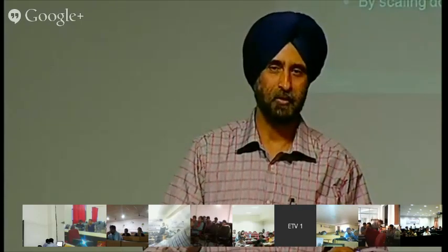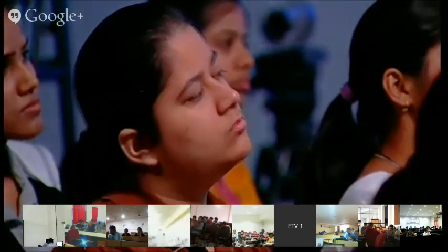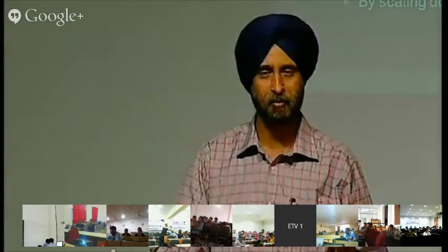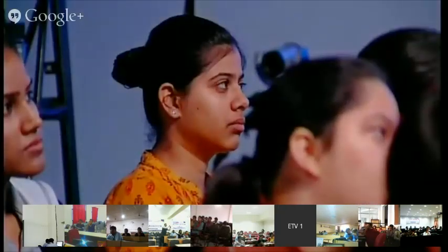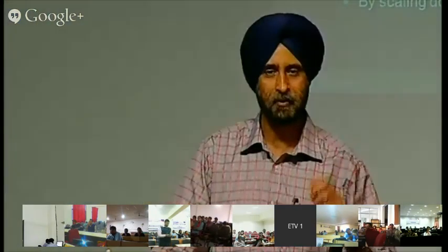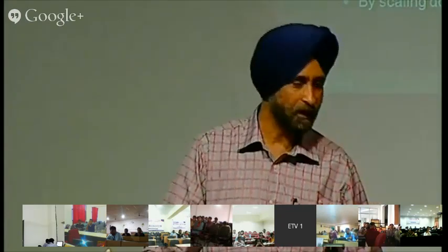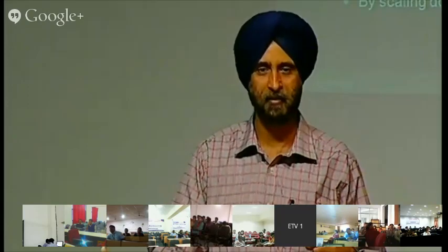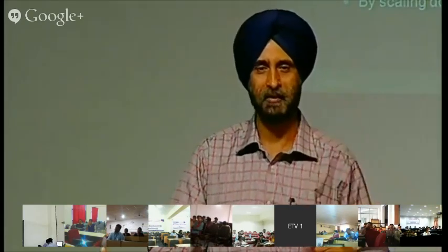Then frequency of clock. Nowadays, in a laptop it is 2 gigahertz, 2.4 gigahertz. In a mobile phone, the same, 2 gigahertz, 1.5 gigahertz microprocessors are used. The microprocessor may be 2 gigahertz, but if you are doing something like addition or subtraction on a mobile phone, you need not do the operation at 2 gigahertz.